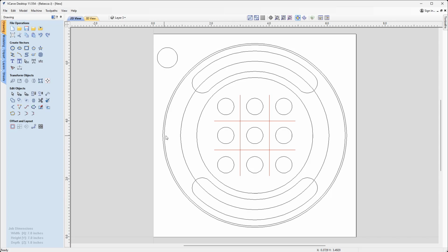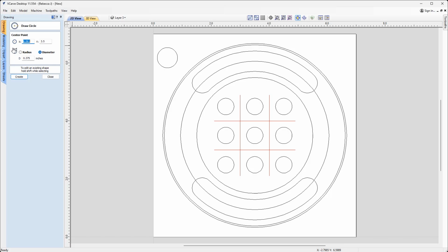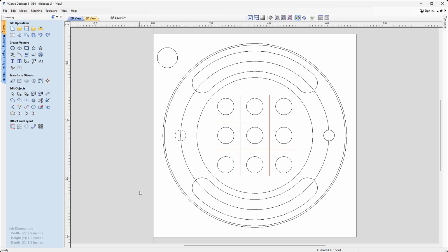And so in order for us to close them off together, I wanted to include magnets here. So we're going to look at applying a magnet position on the left and on the right hand side of our ring. We're going to use the draw circle tool in order to create the diameter of the circle that represents our magnet, in which case I've measured my magnet and it's come up as 0.375 in diameter. Obviously, if it's different for yours, you will need to change this value. I'm going to snap to this point here and click there, snap to this point here and click there, and there are my magnet positions. Okay, so we're pretty much done with this sheet.